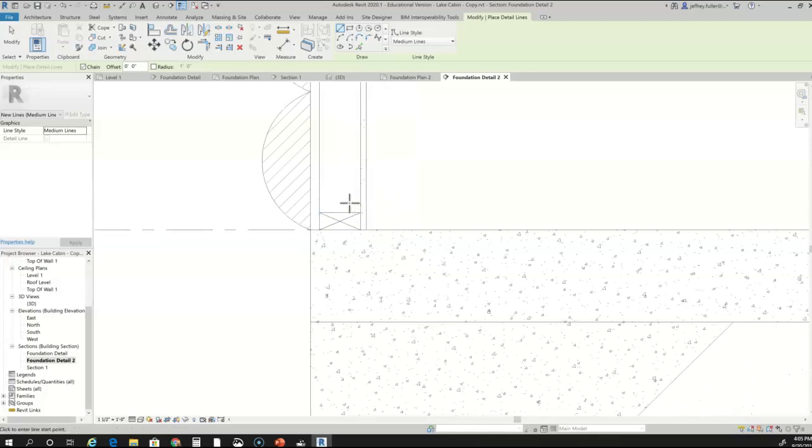Okay, next thing I'm going to do is actually draw the anchor bolt. So I'm still in line tool, which is good. I want to mark the extent of my J-bolt. Now this J-bolt has to be at least 7 inches deep. Some people will put them deeper. It may be deeper on some parts and not as deep on other parts, but just 7 inches. Keep that in mind. So I'm going to start at this point and just kind of pull my mouse down till I find about 7 inches. Click, and then I'm going to drag across. That line is just used as a marker.